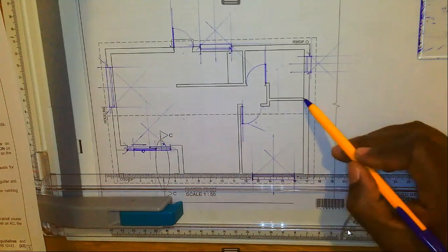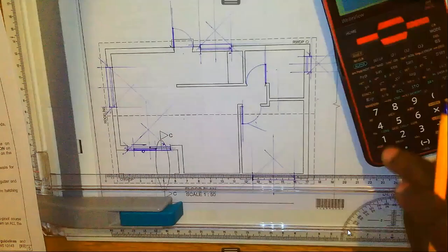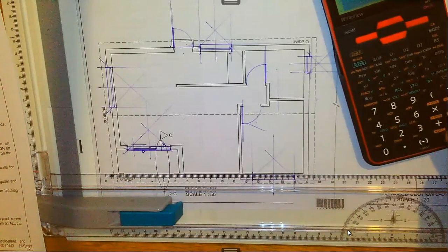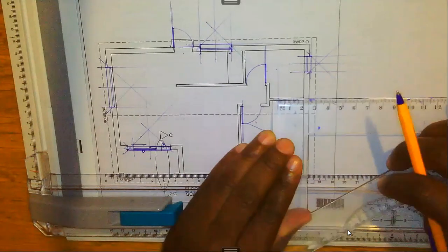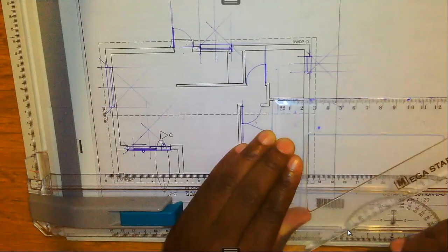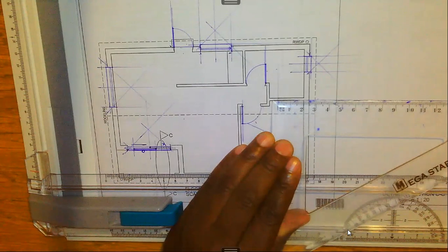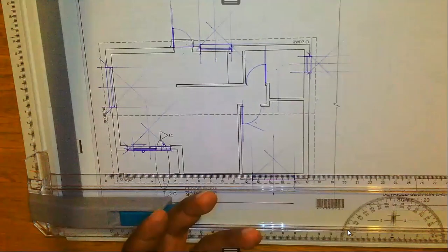If you want to verify that, you can do 1,000 divided by 50. You'll find that you get 20. So let me take an ordinary ruler and check. The distance from here to there should be 20, which is exactly what we have. So when you have got a scale rule, it's fast because the graduations are there. You are not going to divide or multiply by anything, it's already available.